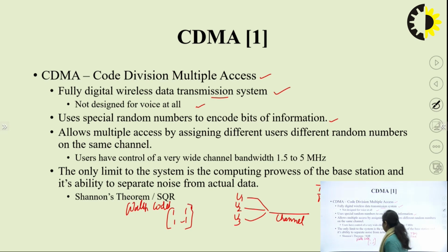So, that is the Walsh table. Here you can see these elements are 1 and this one is minus 1. Let us say I have a 2-bit code that I want to transmit, let us say it will be 1 and 0, then it will be matrix multiplied by these elements, and then this will be the output, the Walsh code.